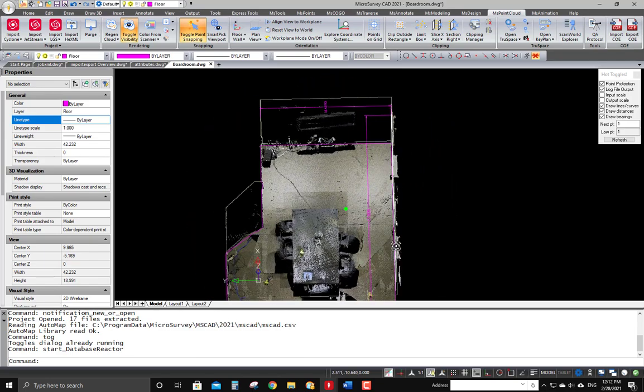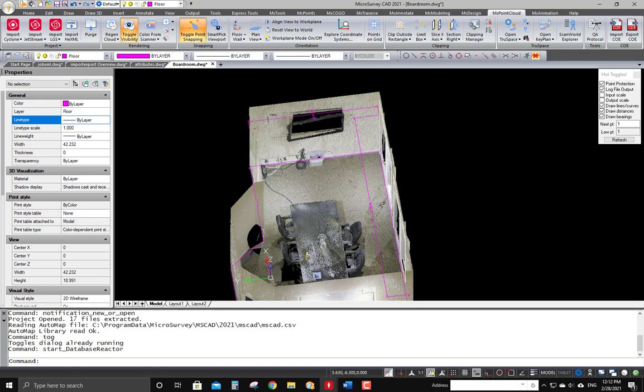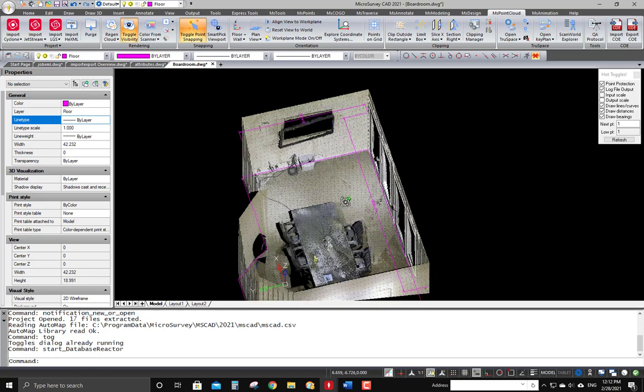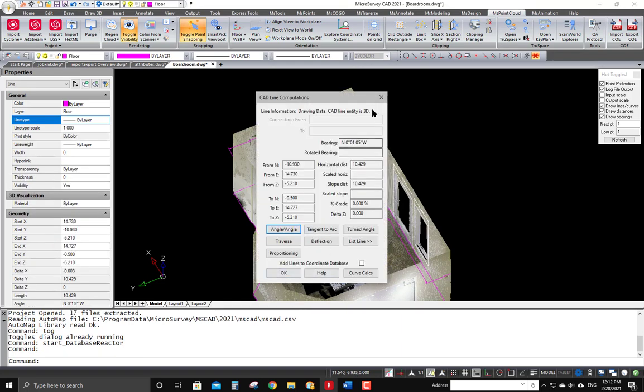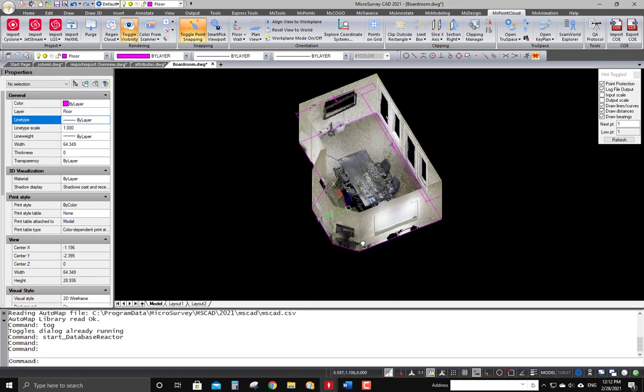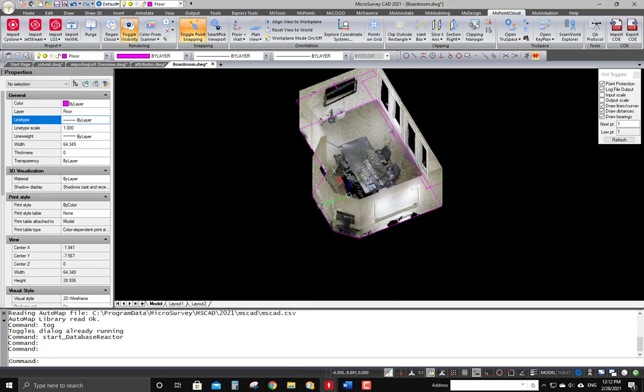And this will kind of allow me to show you a few of the more architecturally oriented tools. And once you've got a point cloud loaded up, what you'll find is you've got lots of tools that allow you to assign an alternate UCS within the drawing to make it simple to perform drafting tasks. So in this example, I've used a tool to generate a UCS that represents where the wall and the floor meet, and that made it very simple to plot a polyline that goes all the way around the perimeter of the room.